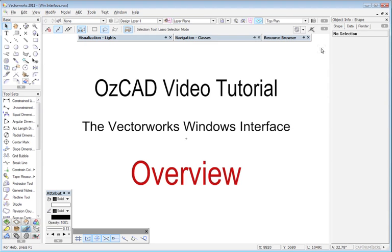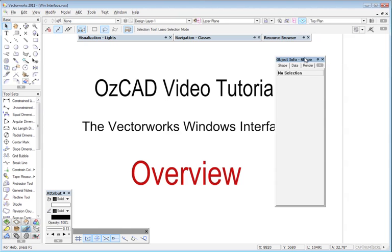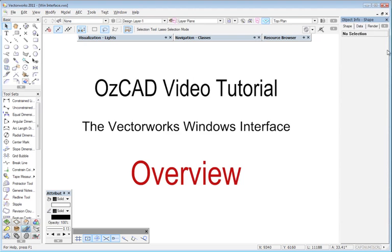Now on Windows we have what's known as palette docking, and this allows the palettes to be absorbed into the edges of the drawing window. This object info palette here, for example, is currently docked on the right hand side, and if I were to click up here in the palette title and drag it out of here, you'll notice that it switches to a floating palette like these other palettes I've got here. If I put it back over there, as I get the cursor close to the edge of the drawing, you'll see it will jump back into that place, and if I then release the mouse, it will be docked.